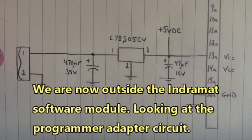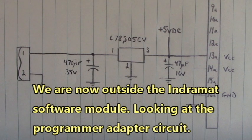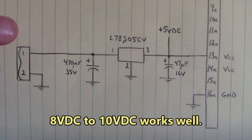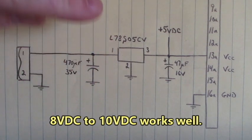Here's the connector where we bring our DC voltage in. We have an L78S05CV, and you can use any 7805 in the TO220 package. We bring 8 to 10 volts thereabouts into this voltage regulator.